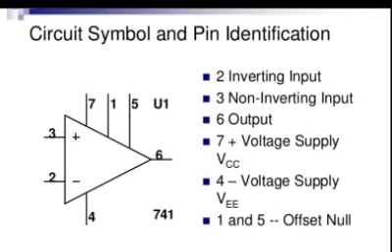This pin configuration is very important because in the lab you have to connect the voltages, and you need to make a pin grounded. So for that you need to know which pin is inverting and which one is non-inverting. So give attention here.